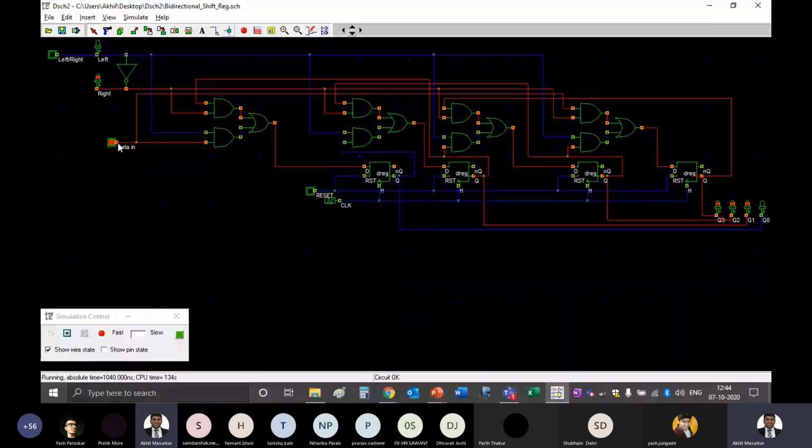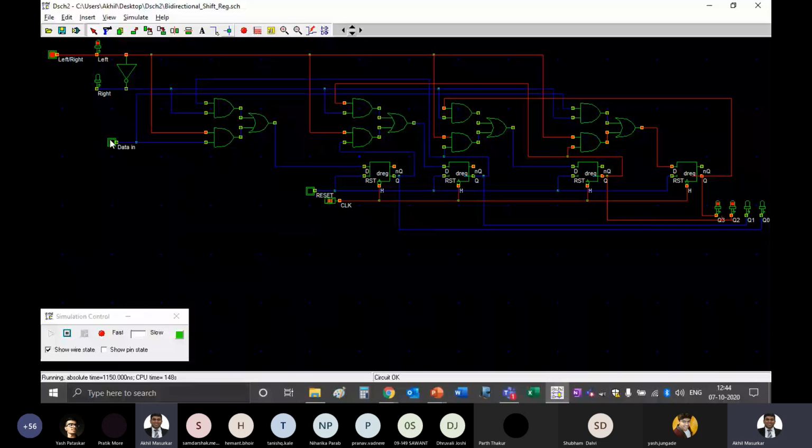So again, you can see that this is right shift, and now if I want left shift, let's make this thing 0. See, now from the left side it is going to shift. So I want many times left shift, because when you have done programming in C, you have these instructions. Many times you have to rotate an array. So how to implement this instruction at the hardware level? To support this instruction, you should have such a facility at the hardware level.